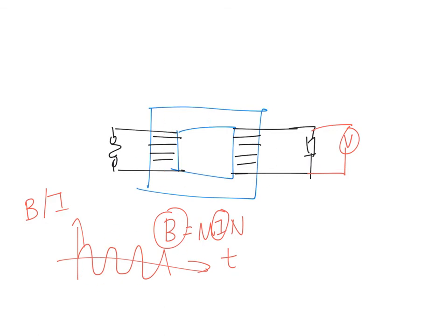The soft iron core, having soft magnetic property, will be easily magnetized. The function of the soft iron core is to concentrate the flux. How does it achieve it? It gets magnetized as well. When the soft iron core is in the magnetic field, it will be magnetized, so it will modify the field of the solenoid. Without the soft iron core, the field of a solenoid, if you draw a middle line, half will go here, half will go there. But because the soft iron core is magnetized, it will transfer the flux. Most of the flux will be transferred to the secondary coil, because the soft iron core goes one round, which means the whole thing becomes magnetized.